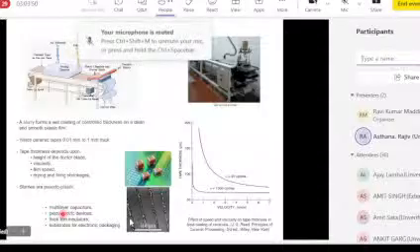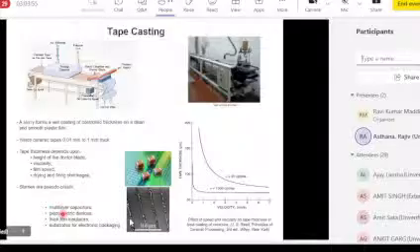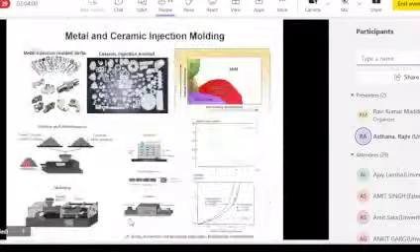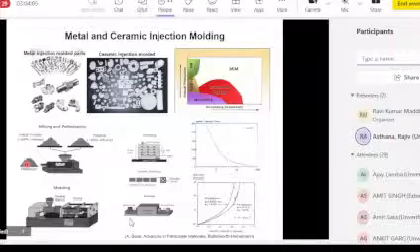People were using thermal debinding earlier, but thermal debinding caused distortion and cracking and everything. So now people use catalytic debinding, which means we use vapors of a catalyst, an acidic solution, to leach out, to dissolve the polymer. And after that, you get a very porous part, a so-called brown part. And that brown part is sintered to develop full strength. During the heat up of the debound part, the minor binder will burn out while the powder particles just begin to sinter together. When sintering is complete, you have your fully dense part.